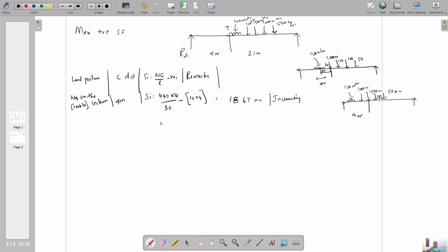Actually, why are we moving the load to the left side instead of right? Because the vehicle is moving from left to right, and we are considering some tail portion here so that all the loads are in front. So there is no meaning in moving this load in this direction further. If we want a trial, we have to shift one load in the left direction only, in maximum positive shear force.